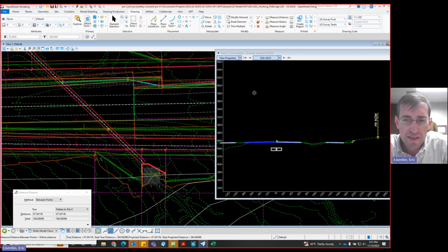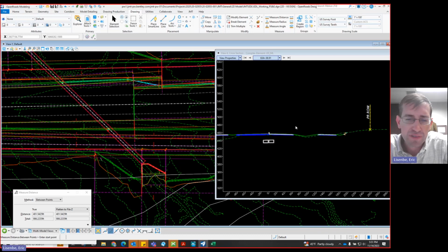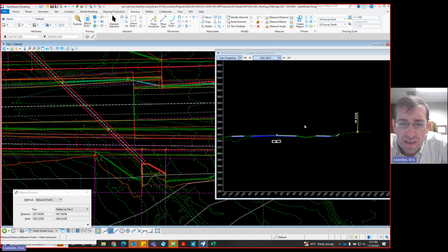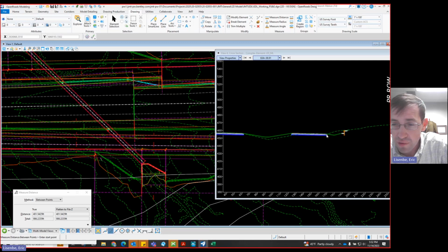So one of the things that I get asked is what to use for your deck editor information, your overtopping profile. And you have some options. Unless your model is overtopping the roadway, it's not going to really affect the results. And so it's really, what do you want to see? So in my case, we've got a pretty typical scenario of a frontage road that is lower than the main lanes. And so I'll often want to see and double check our elevations against this low frontage road pavement profile.